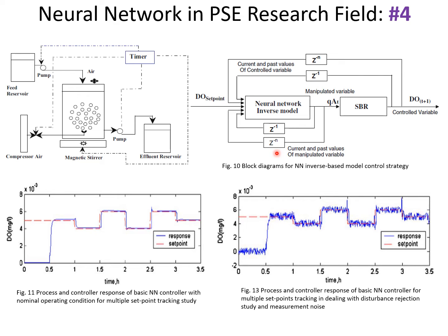As mentioned just now, it was tested for different set points and also different disturbance and noise to make it robust. As I said before, we have not only set point but also disturbance, and we also use other changes like model mismatch and noise to make sure that the system is robust. In this case, first of all, we use multiple set points for the DO, and you can see the response follow from basically no action at all, it doesn't know where to go, starting from zero.